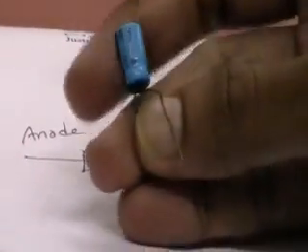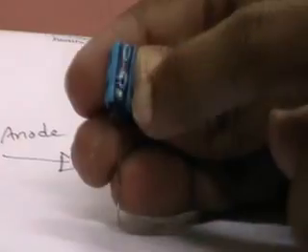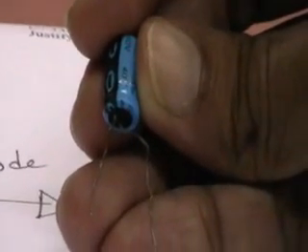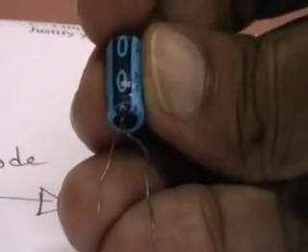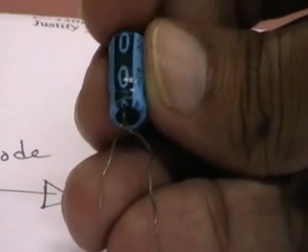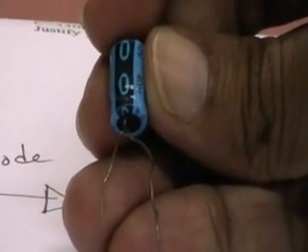Now we will tell about the capacitors. This is a different type of capacitor, not the ceramic type. This is the electrolytic capacitor. So this black streak indicates that the terminal close to it, that is the short wire, acts as the negative terminal. The other side, where there is no negative streak, acts as the positive one. So this is the electrolytic one, that is a polarized one. When we are connecting this capacitor in the circuit, we have to be careful and connect it correctly.